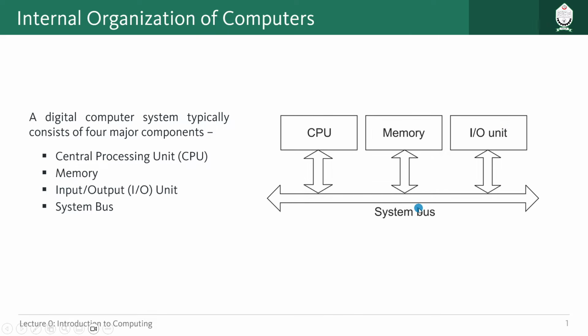And in the case of a microcontroller, everything is actually built in an integrated circuit, right? Everything will be in one chip. But for a microprocessor, this CPU itself can be found as a chip, an IC. But if you want to make this microprocessor work, you must connect memory, input output unit, and different other things to make it work. That is the main basic difference between microprocessor and microcontroller.